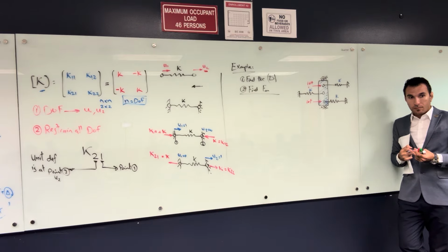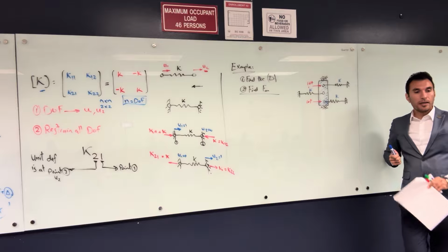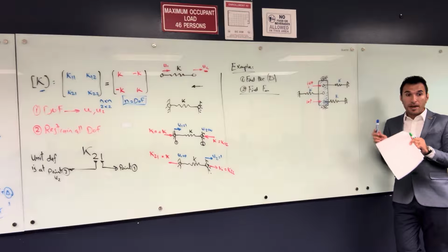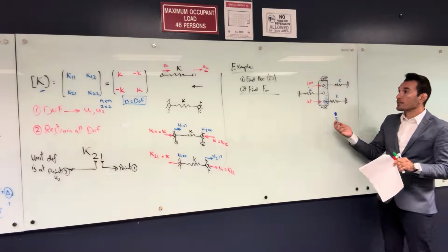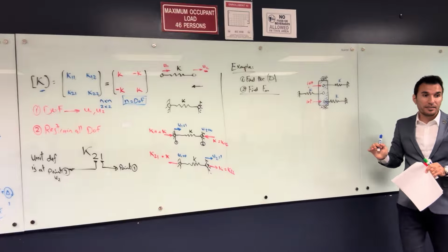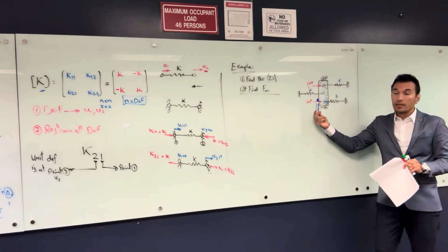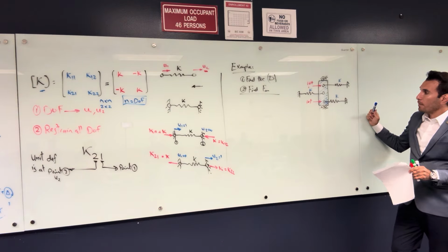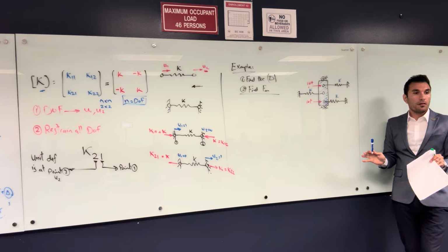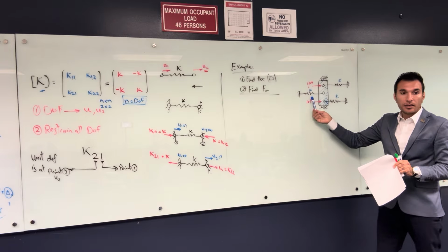Because you have P equals K delta, so you divide by K and you get delta. Why 3K? Because they are all the same and all in parallel. Right now you only have one delta, so all these springs are going to have the same delta. Some of them are going to be in compression, some in tension. They all are going to have the same force, two of them in compression and one in tension.